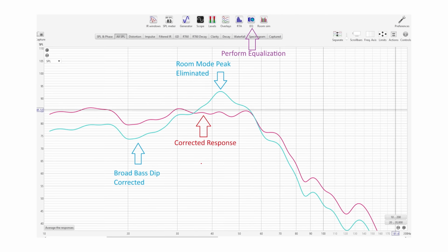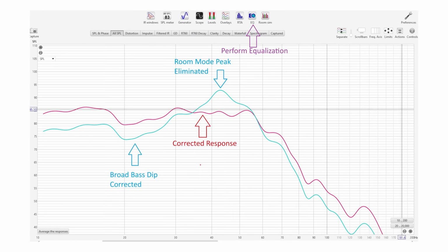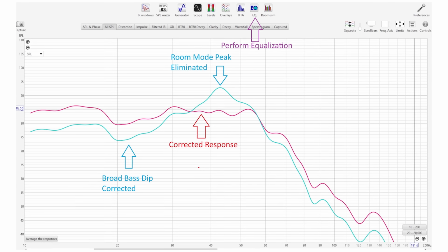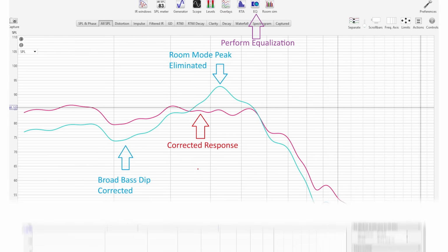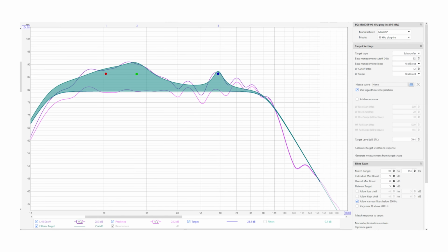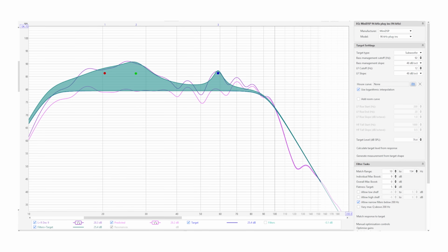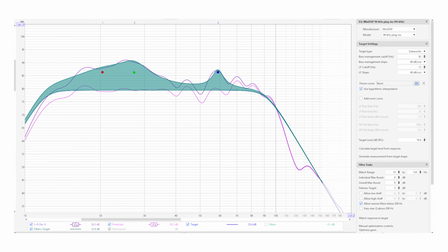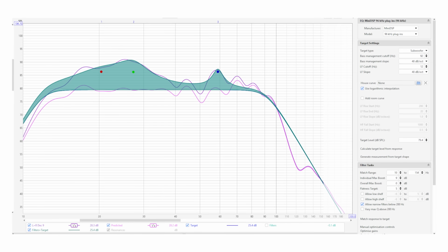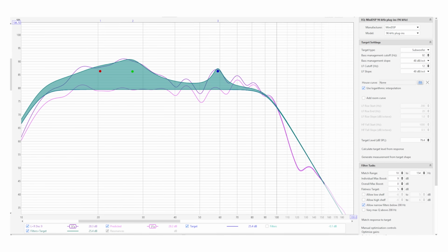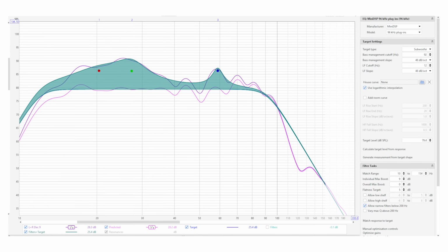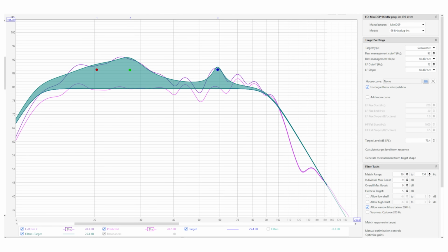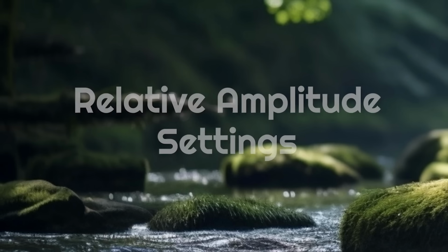The blue line represents before REW equalization, while the red line shows the corrected frequency response. This example is for one subwoofer. Each subwoofer can be calibrated independently by making a sweep and then going to the EQ page of REW to generate the correction filter. REW calculates the filter coefficients, which you then download into the PEQ menu on device console. You can find more details on how to perform this correction in the REW help guide.